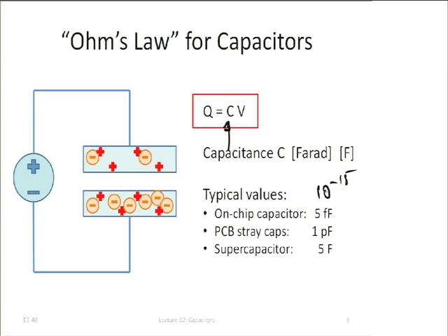Okay, and on the printed circuit board, what's a printed circuit board? Is that usually green or brown stuff, right? That's in our electronic gadgets where we have all the components soldered to. Just by soldering a component somewhere, we typically end up with a capacitance on the order of picofarad. What's picofarad? Pico? 10 to the minus 12, right?